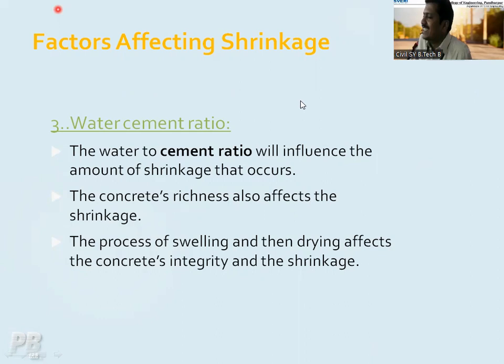It is absolutely in our hands to have good quality concrete for the execution. But we can't control the creep which is going to happen in the concrete body. Creep is nothing but deformation. And why is it going to happen? It is going to happen due to the load which is acting on the body for a longer duration. Maybe your structure lasts for 10 years, 20 years, 30 years. So as the age goes on increasing, there will be some deformation.